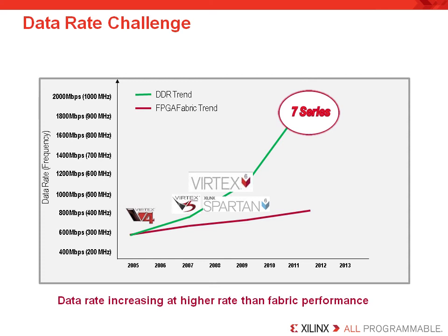To compensate, designers will try to widen the data path to 32 or 64 bits to improve the data throughput. But the caveat, of course, is pin layout, power consumption, and cost of materials associated with high pin count packaging and the use of slower I/O standards. So just widening the data path is not a solution for the newest technology.